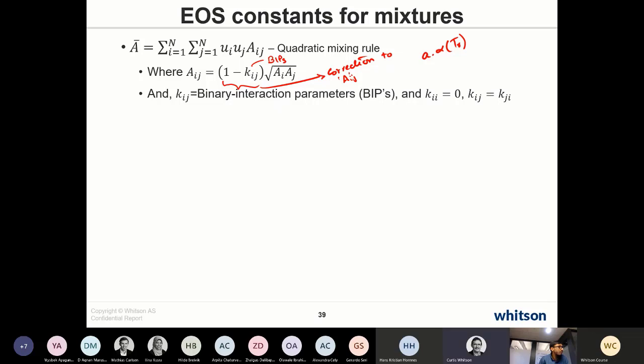Well, the story is a bit long, but basically the original introduction of the binary interaction parameter, BIP, was by Prausnitz and his co-worker or maybe student Chueh. And when they originally did it, they used the term small l, Lij, for the entire 1 minus Kij. They didn't use 1 minus Kij.